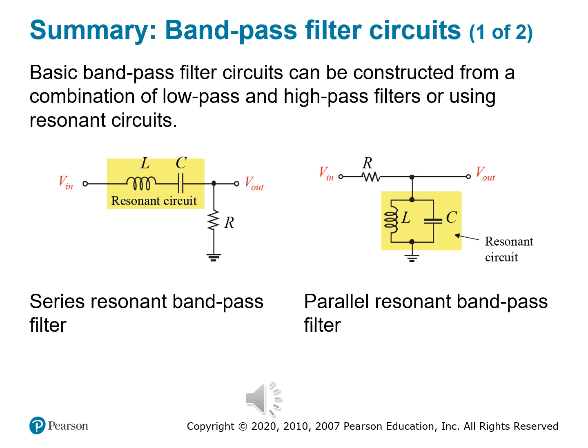All right, so on this slide, you're going to see two approaches to bandpass filtering: a series resonant bandpass filter and a parallel resonant bandpass filter. Let's talk about each one independently. With the series resonant bandpass filter, you have an LC series resonant circuit placed before the resistor. At resonance, that LC combination has a minimum impedance, and that allows the desired frequencies to pass. Frequencies outside of this sweet spot are blocked.